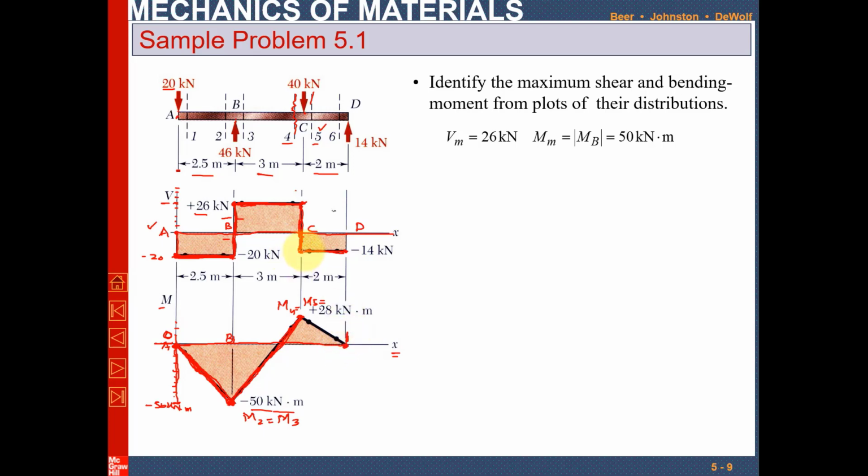Again, this is the shear force diagram. Between C and D it is a constant line, so it will be up, and it is negative, so definitely it will go downward. There will be a downward line, so this will come to 0.